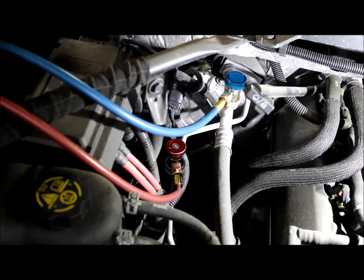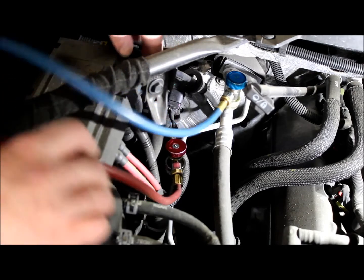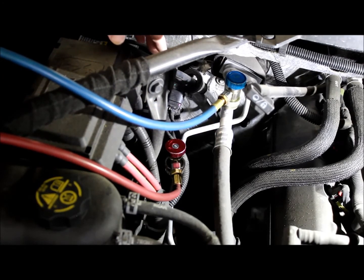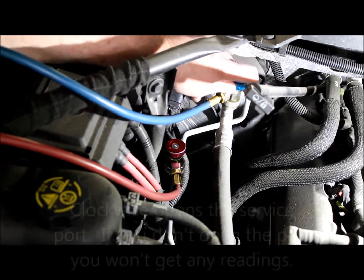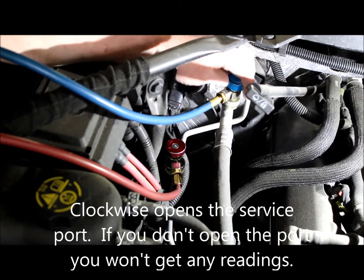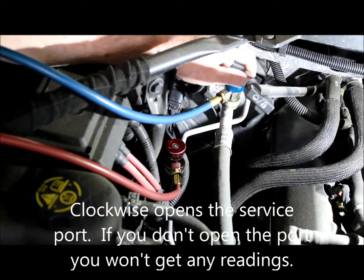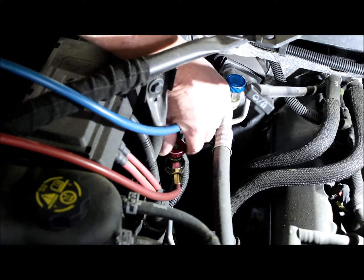I've now connected the high and low side hoses to the service ports. The low side hose and valve, you'll notice, is blue. High side is red. Before we can get any readings off of these, we need to open the valves. So by turning the knob clockwise, that will push on the Schrader valve inside the service port and allow the pressure inside the system to reach the gauge on our service equipment.